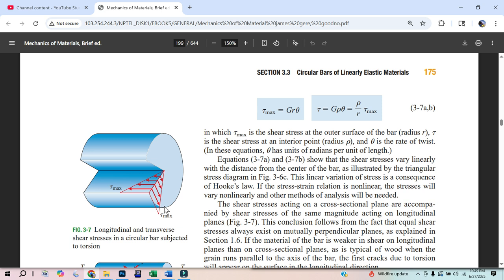And this is where I would want to break out my drawing and writing skills, just to show it. Shear is still like a leveraging of molecules, because if I drew those four molecules and sheared, one side up, one side down, what happens is that two molecules get farther apart and two molecules get closer together.